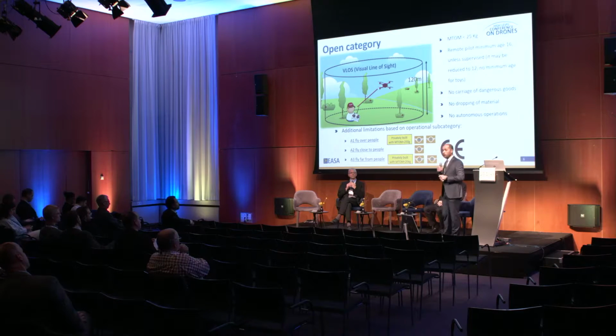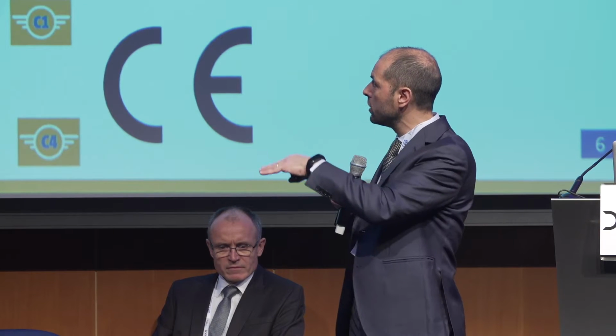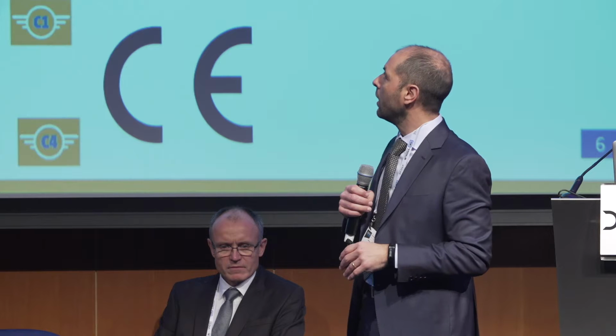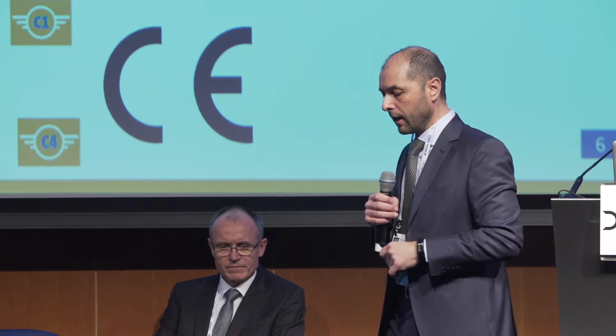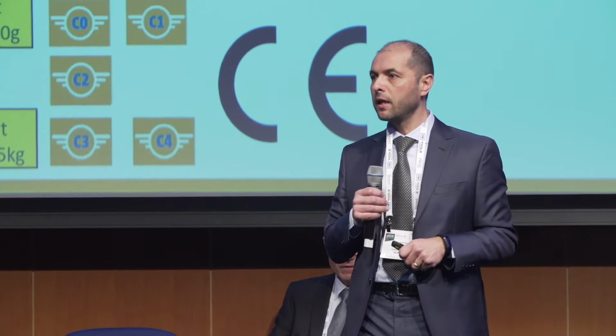Then operations are always below 120 meters. 120 meters from the takeoff point, so using the orography of the area where you are flying. And in general, we have maximum takeoff mass less than 25 kilos, and the minimum age is 16 years old.